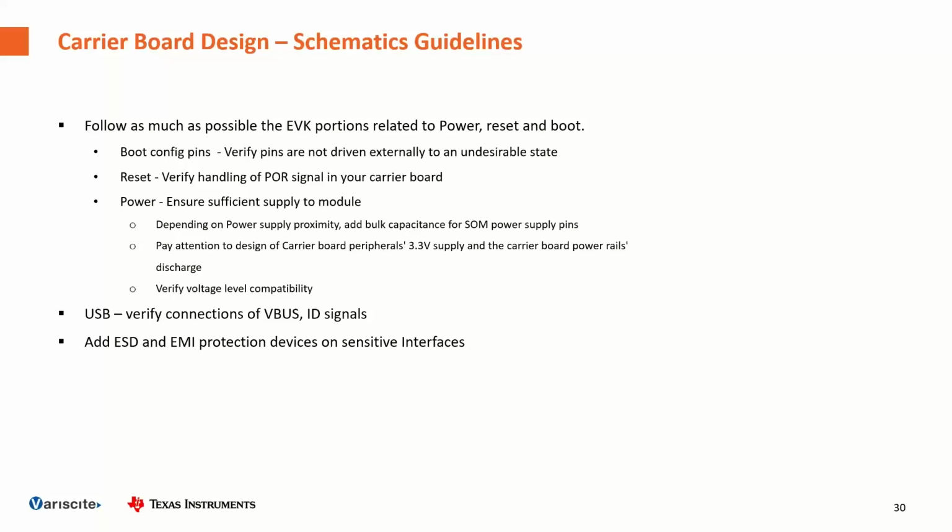Another critical part is the reset. The POR signal in the carrier must be coherent with the SOM expectation. So if you use the reference implementation on our carrier, you will have no problem. But if you need any custom implementation, feel free, as long as you respect what is detailed in the SOM datasheet. Pay attention to the power section.